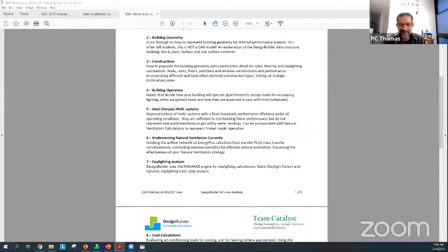Very nice question. I think the only tool that used to be able to do it was Ecotect. Does Grasshopper have some way of doing that? Definitely, Grasshopper has plugins called Ladybug and Honeybee, which would help us do the insolation analysis as well as calculate the angle we would require for shading. There is that possibility. Within DesignBuilder, you can test all the shading devices you want.